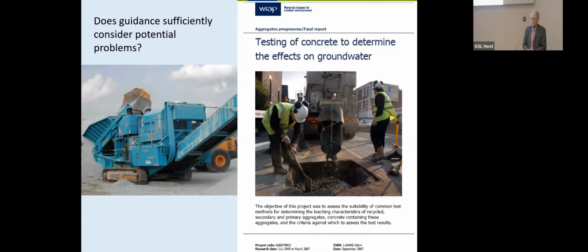Your point about the aluminium, it all comes just from the cooking foil, the baking foil we all use every day in our homes. What happens to that is very weak. It's in tension, it goes into the flames, and a lot of it ends up in the fines, where it's then very reactive. And particularly if you then take your IBA and mix it with cement, you have got the perfect conditions for expansive chemical reactions.